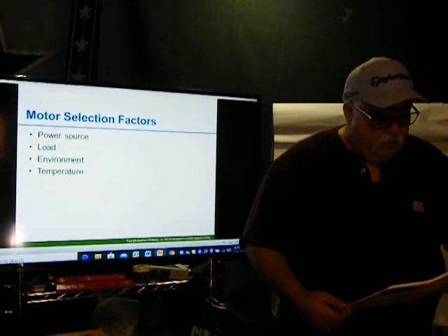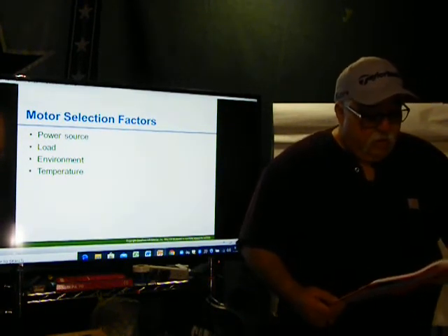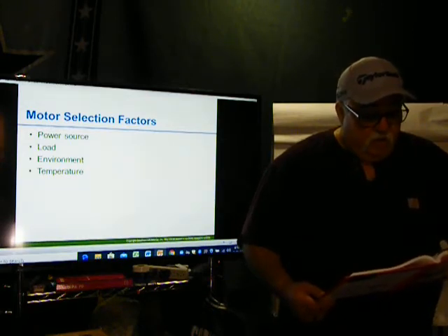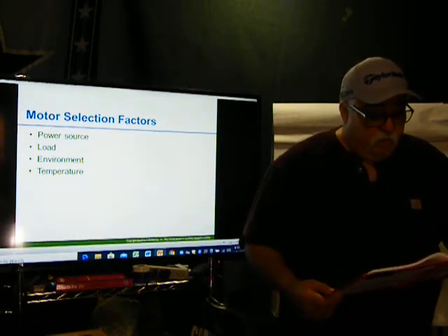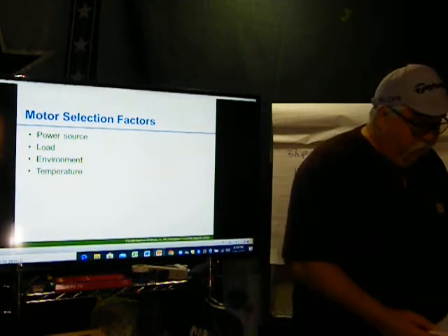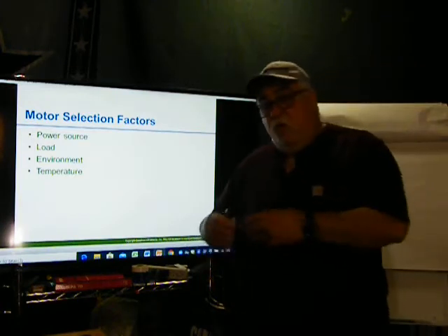The location can affect motor selection. Some motors are more durable than others. Moisture, dust, explosive gases, corrosive chemicals, radiation, temperature extremes, and vibration can be harmful to motors. So again, where's this motor going? What type of motor is it?